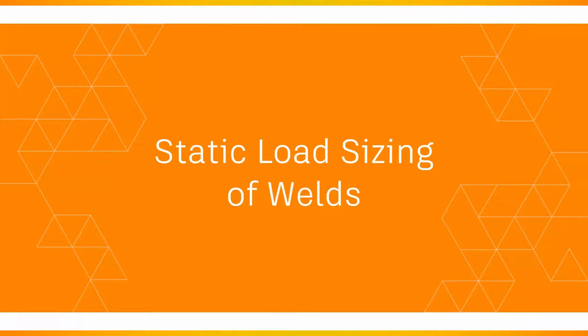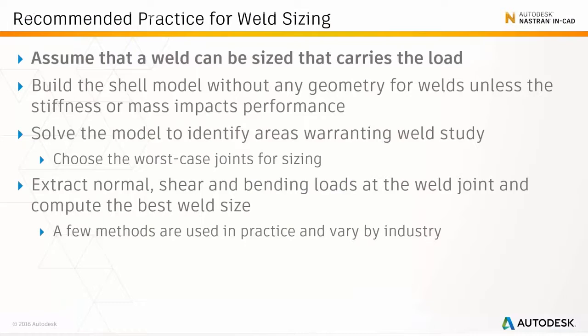So how do we decide loads statically? Well, firstly, we need to assume that a weld can be sized that carries the load, and design your shell geometry without any additional attention to the weld bead itself, unless that weld bead adds, one, significant local stiffness, or two, if it's a dynamic or inertial situation, significant mass to your design.